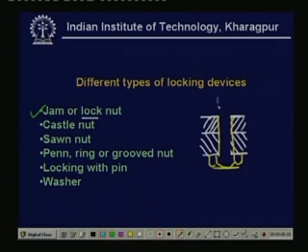Now, instead of having one nut which we will try to loosen, we use two nuts. That is, we first remove this nut, put a small nut, that is a thin nut, one very thin nut, and then tighten it normally. Then on top of it we put another nut. So, there are two nuts which are put one above the other. We tighten the top nut with very high torque, large torque, and then loosen this bottom nut.